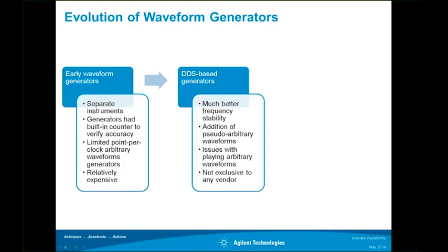The only issue with this DDS-based technology, there's a major flaw, however, is that when you output an arbitrary waveform, the DDS-based technology will actually skip some points. And so that flaw is going to be inherent with all DDS-based generators. Unfortunately, well, I guess fortunately for everybody that has a generator, that made everything cheap, but the generators are all going to have this flaw.